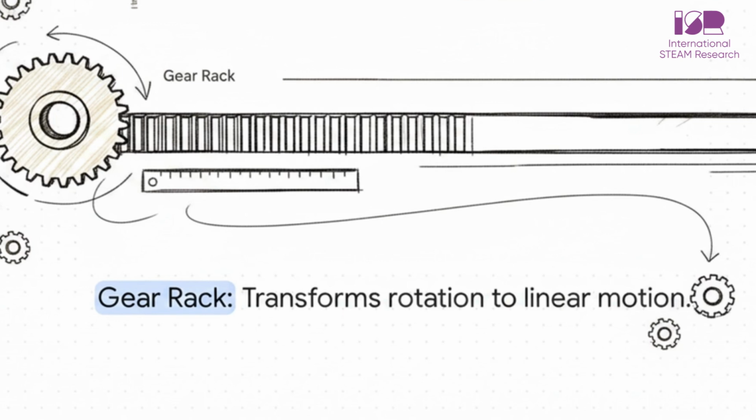Screw gears use a very specific 45-degree twist angle on non-parallel, non-intersecting shafts. That means the 2 rods essentially cross past each other at an angle without ever actually touching. Because the teeth only make contact at a single tiny point as they slide past each other, their load-carrying capacity is minimal. You definitely can't use these for heavy lifting. And because of that sliding action, they need very careful lubrication to stop them from destroying each other.